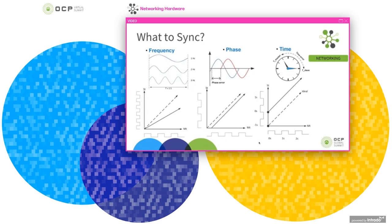We are always talking about time sync, but what to sync? Here we have frequency, phase, and time to be synced. But what's different? For frequency synchronization, if you could not let your system fully sync in frequency, then it will accumulate the time difference little by little until your system cannot tolerate it.